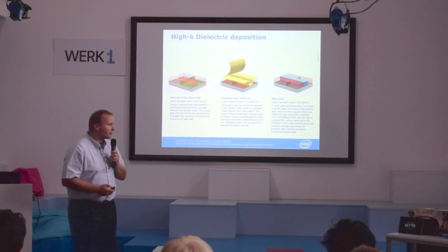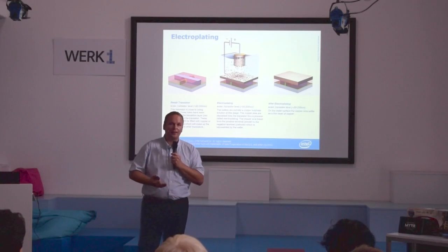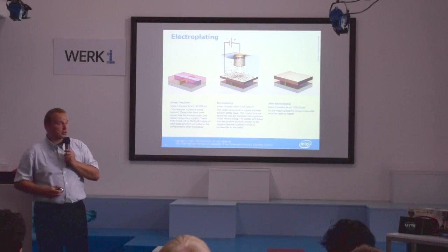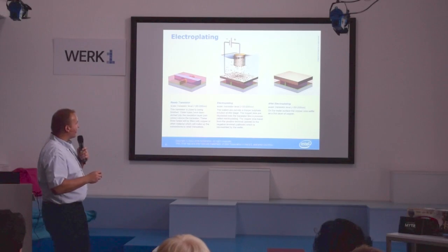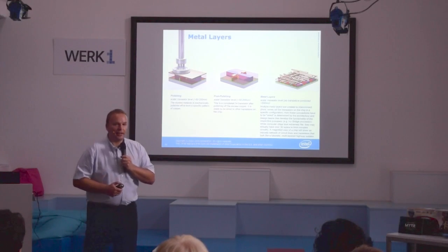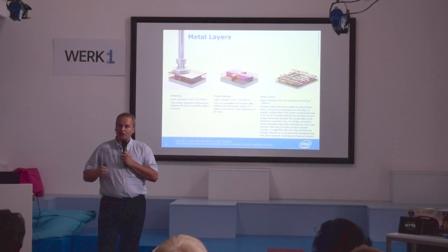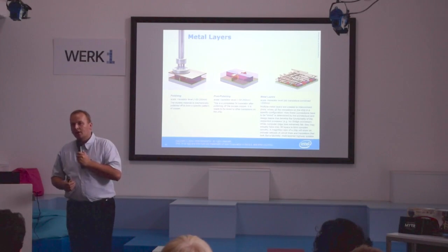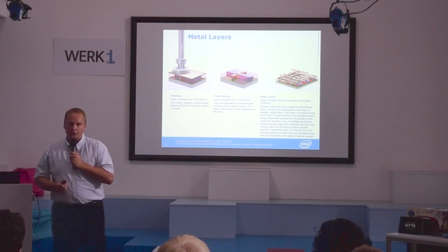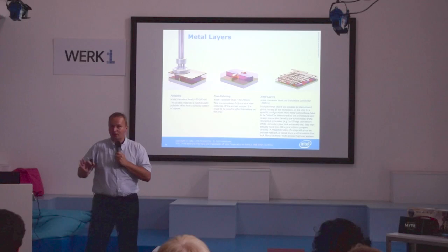With the features we want. And obviously, once the transistor is done, we also need to connect it electrically to the outside world, or at least to other transistors on that processor, and that's done by electroplating and post-polishing and eventually creating the metal layers, which are several-story-high electrical wires that connect the different transistor connections to each other, transistor to transistor, but also to the outside world through the package. If there are any questions, by the way, in between, you can always ask.